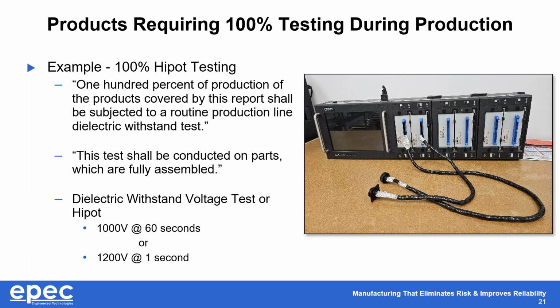That test needs to be completed on a fully assembled, fully connectorized heater. And there are various test conditions, but usually it's 1,000 volts or 1,200 volts.